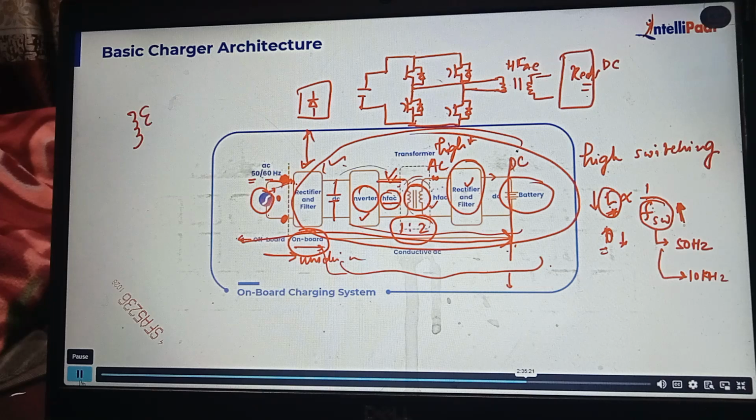If you are having a 50 hertz transformer, voltage can be increased and decreased, V1 and V2, but the frequency of operation will remain constant. Yes, sir. So how can you change it? Voltage. So frequency will not change. Whatever frequency you have chosen, according to that frequency, you have to design the inductor. I hope I have given the answer.